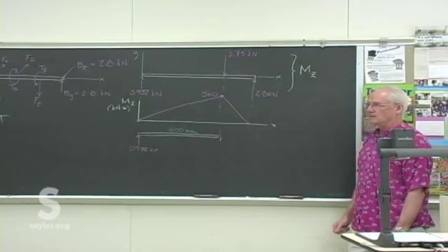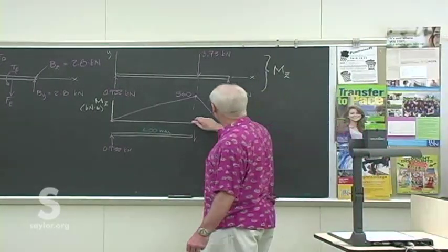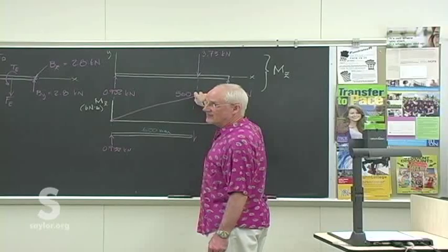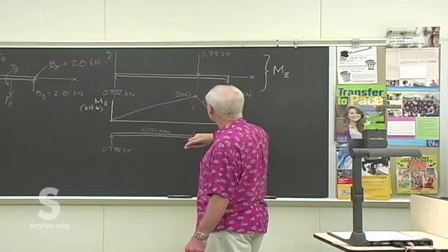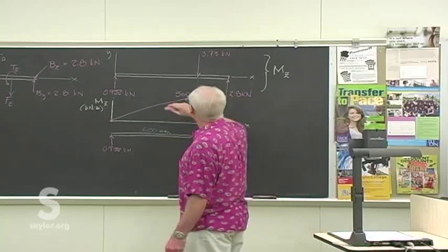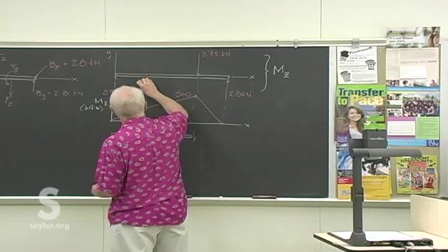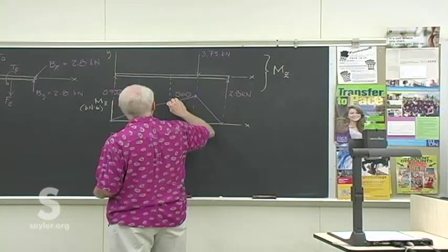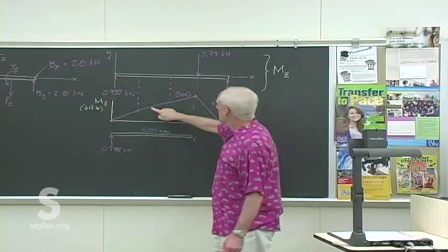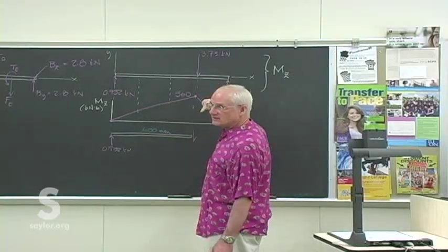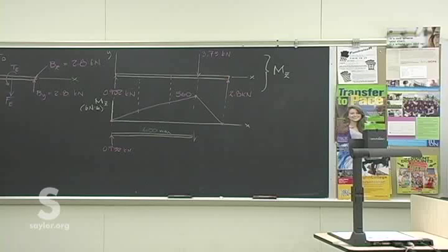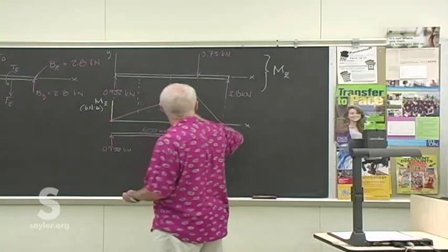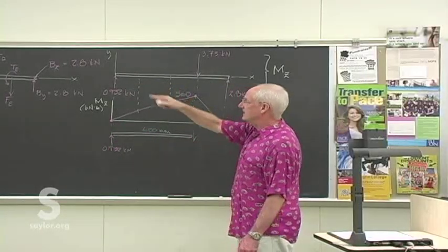for this view. And we see, obviously, in this direction, the worst spot is on that gear E. But it allows us to also find the values at gears C and D. We can then take these values, add them to the values we're going to find at C and D in the other direction, and that will tell us which one of those points along the beam is the worst case. So right now it looks like gear E, but we have to check the other two directions.